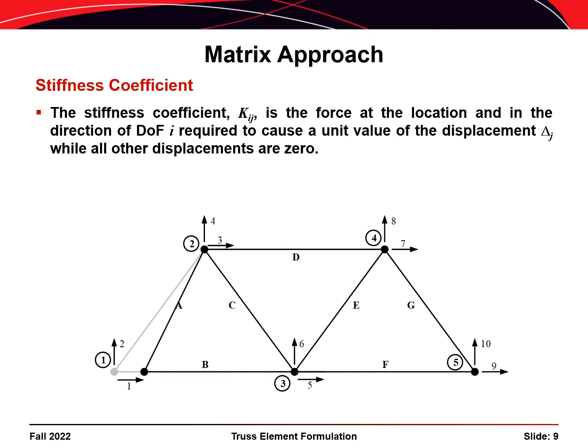In order to do this, forces are required at many of the nodes. For example, we need a force at degree of freedom 1 to push the node to the right, and after we do that, we need a force corresponding to degree of freedom 2 to hold that node from translating downwards. Correspondingly, we need forces at degrees of freedom 3 and 4 to keep node 2 from moving, and we need a force corresponding to degree of freedom 5 to keep node 3 from moving to the right. There are theoretically forces corresponding to the other degrees of freedom, but they would be zero in this case.